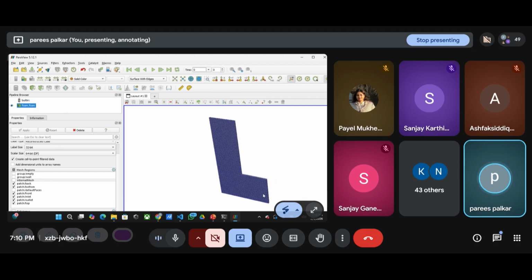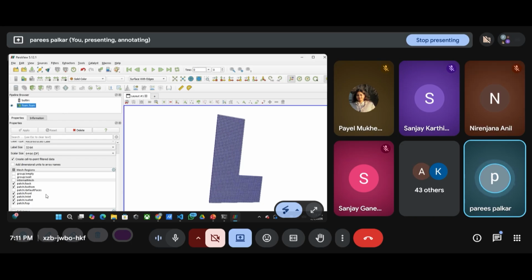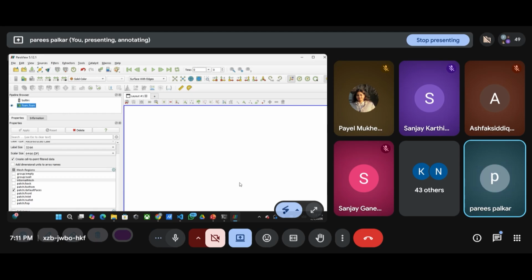Okay, so we have got our mesh. Keep in mind this is watertight, meaning that water cannot go out or away from this. This is a watertight geometry. We are just using a filter to view our patches. Let us see, if I hit default patches, unselect everything and apply, there will be nothing. As we have selected every other patch of our region, there is nothing stored in default faces.